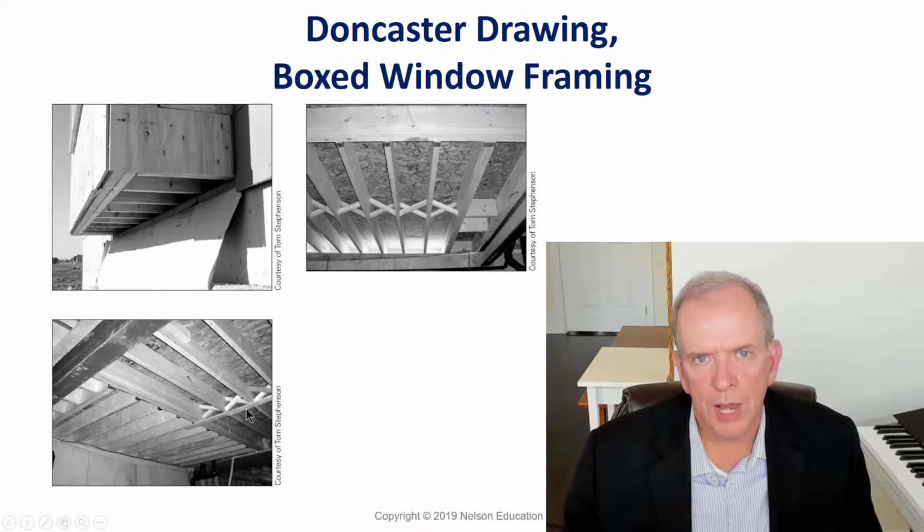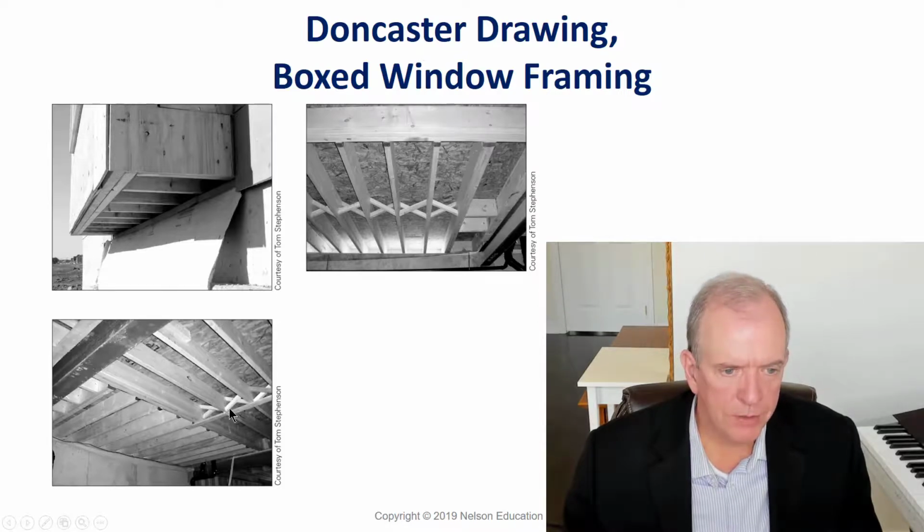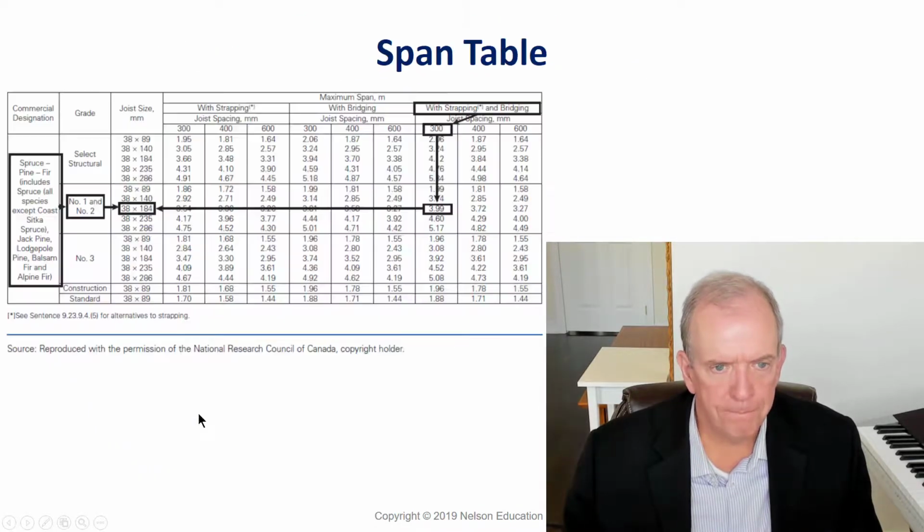You're only going to really use strapping in a basement condition, right? And if you finish the basement, then you just finish the strapping across so you could screw your drywall to it. But that gives you more strength for the spans of the floor. Probably the drywall will be strong enough with it. So that's using strapping and bridging.